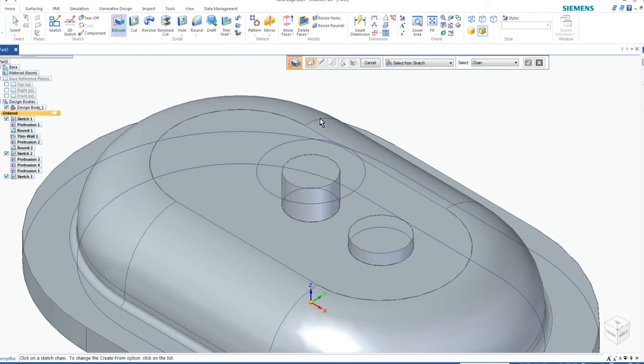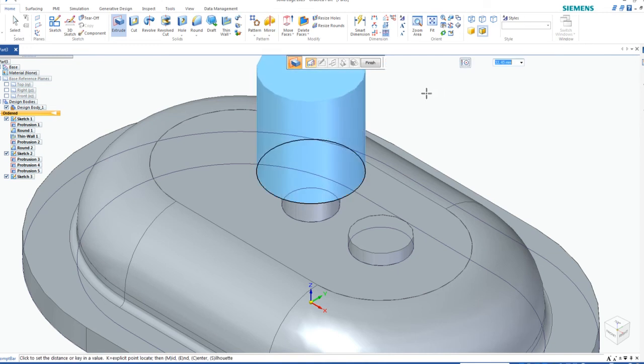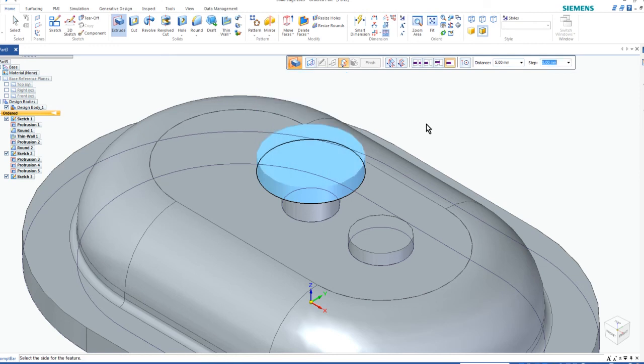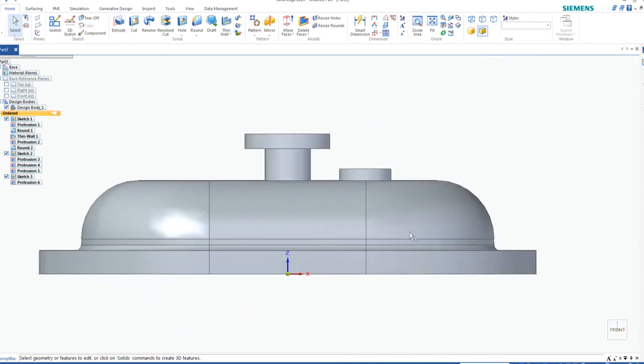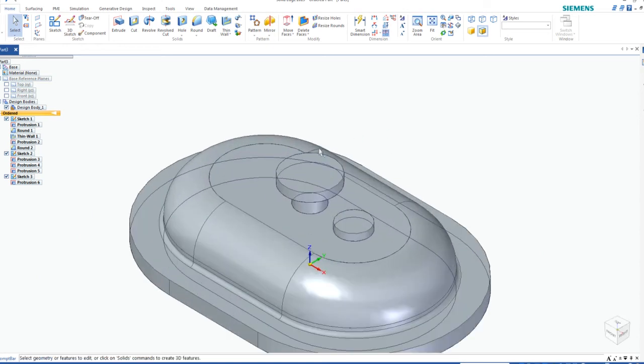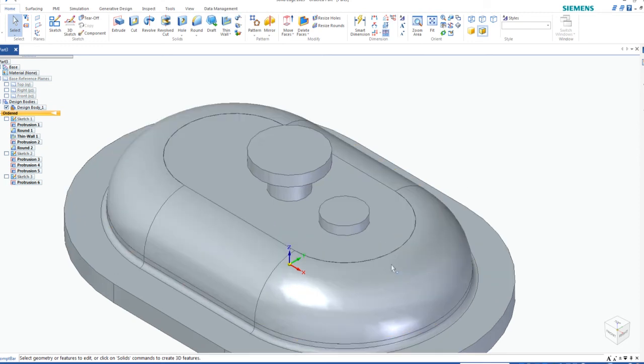Let's go to Extrude. You're going to select the new circle, accept it, go up, and we have indicated, because it's coming off of the drawing, it is 5. So we're going to type in 5, pick anywhere in space, finish, and close. Okay, so now we have that. It's looking good. Okay, as always, like I said, just to get rid of some line geometry, just simply turn the sketches off on your history tree, and it just makes it a little easier to see.